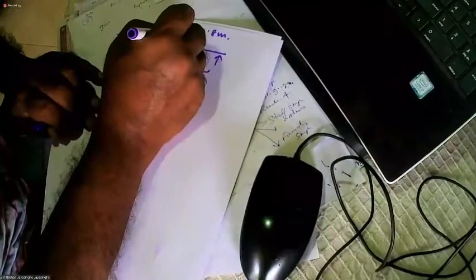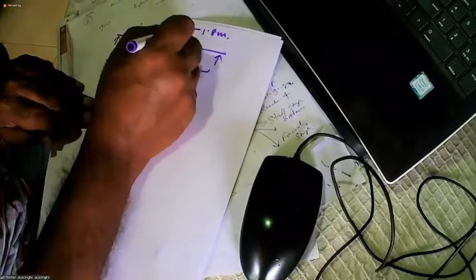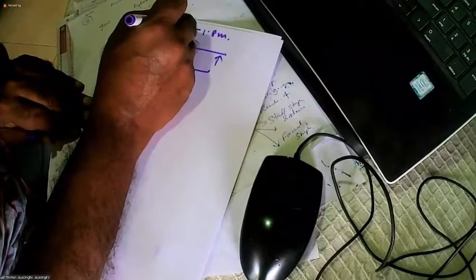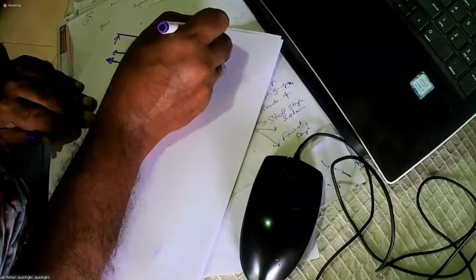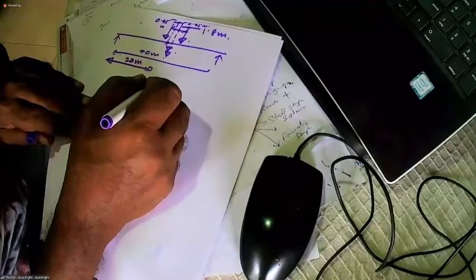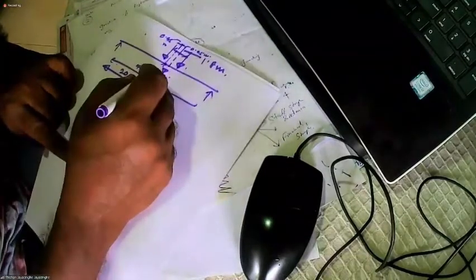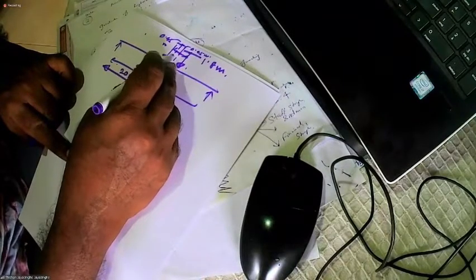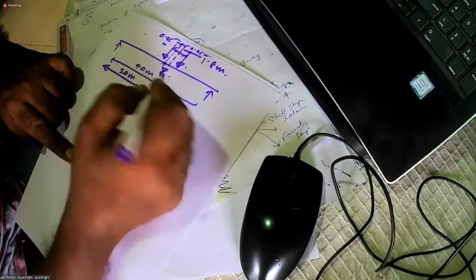And you will make sure the center of the bridge, that is the 20-meter line, is equidistant. So this is 0.9 meters here, 0.45 meters, 4.45 meters. When you do this, you get the maximum bending moment due to these two. When one wheel is on one side, the resultant is on the other side.